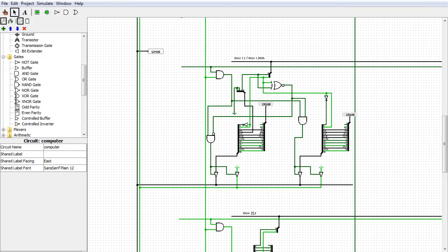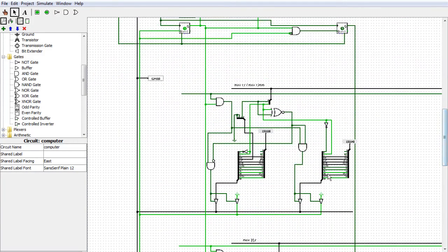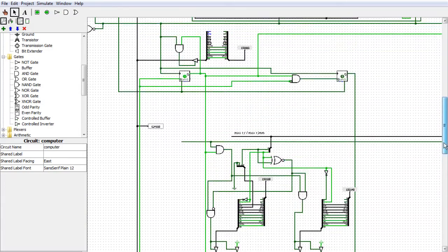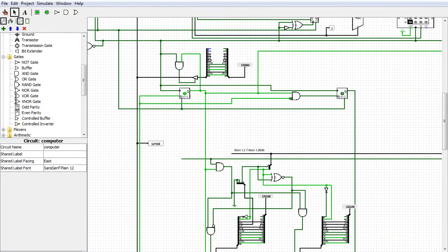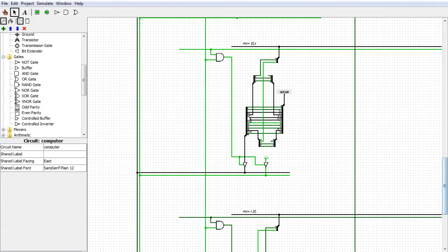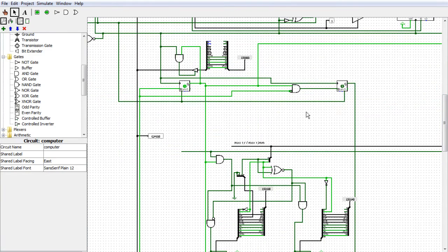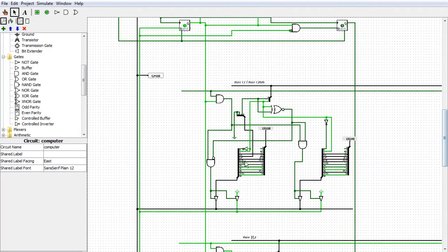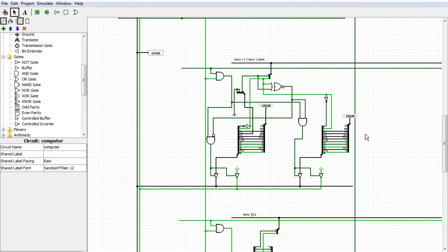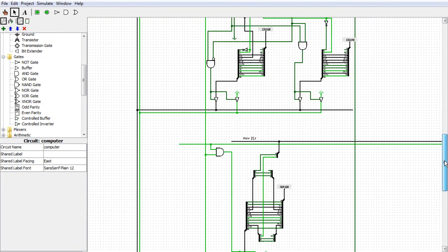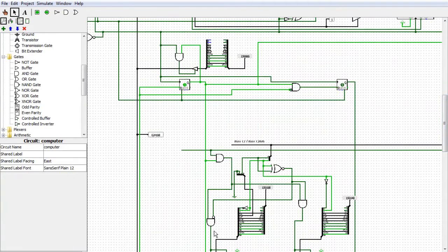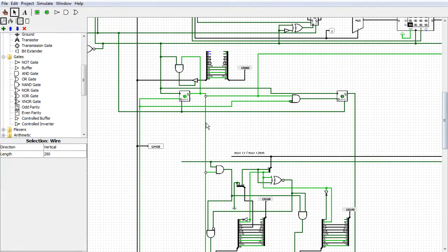Now the reason why it didn't break was because it just so happens that these guys were trying to drive the same line to the same values as these guys. But once you try to store to memory, now you're driving it to different values. You're going to collide with this guy. All right. So the way this works is, first of all, now everything has to drive those lines. We can't have any disconnected portions. That's rule number 1. Rule number 2 is for the first phase, phase 0, this can only go active in the second half of the first phase.